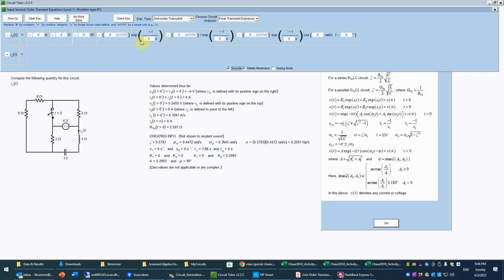However, we actually have a choice of 3 different terms here for the transient term. So this one is basically a simple exponential decay with a constant prefactor, and you can choose the units to be appropriate. This one is an exponential, but it's multiplied by a t prefactor, and so that's, as you may remember, that applies when you're critically damped. And then this is a decaying exponential multiplying a phase-shifted cosine, and as you may remember, that's appropriate when you're in an underdamped circuit. So you say, well, how do we know which of these to use?